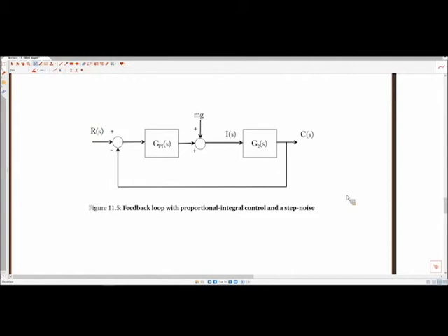That would be another dangerous thing about integral control: it's going to continue to build energy. So a soft thing like people's hands would just continue to build energy and crush those things. But we'll show this. I'll hold this in position, and you'll see how it continues to fight my hand when I put some external torque on it, continuing to build energy in the system. Say, for instance, if we were to pick up a mass with my mass spring damper system, and it's going against the direction of motion, it can then counteract this mass.